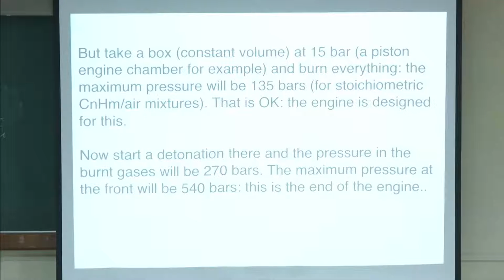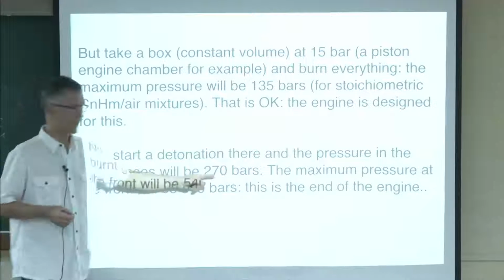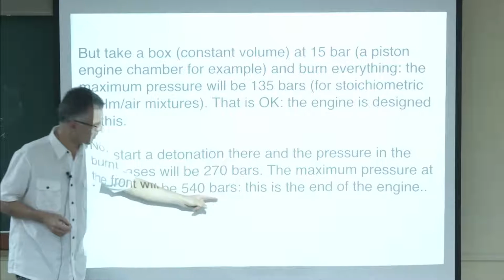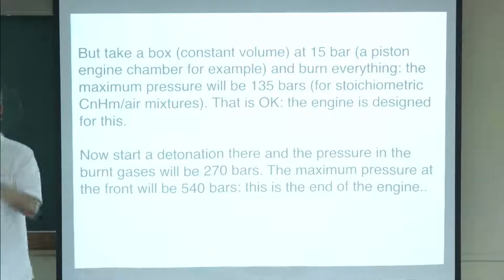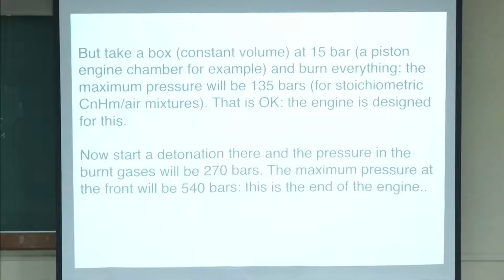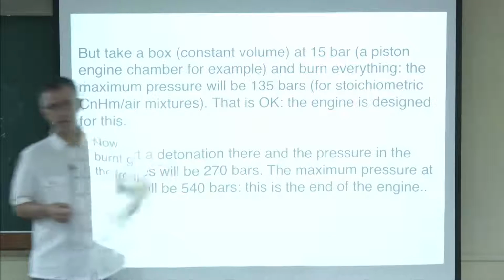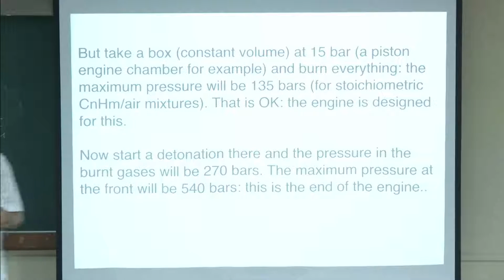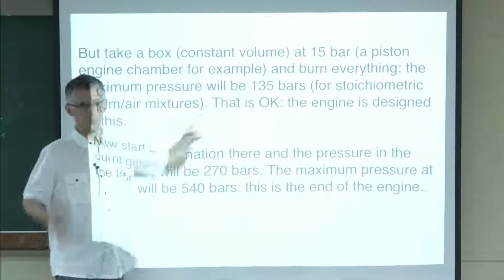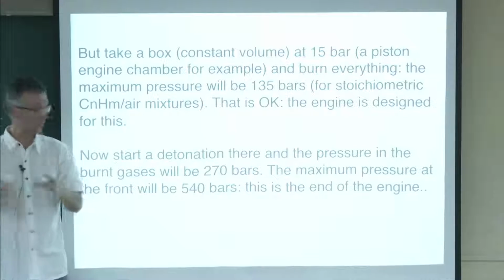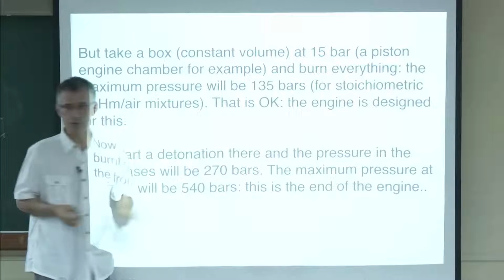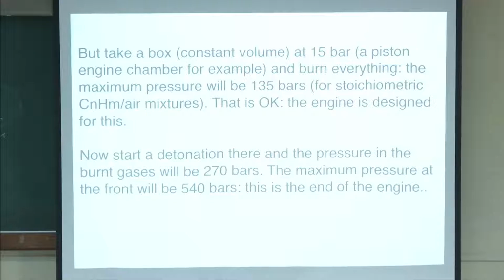But if for some reason detonation begins in this engine, then the pressure in the burned gases will be 270, and the pressure at the shocked state will be 540 bars. Which really tells you that if you're an engineer and you only compute this pressure, you're losing something. If detonation begins in your engine, it's not 135 bars that your walls have to be able to resist. It's 540.